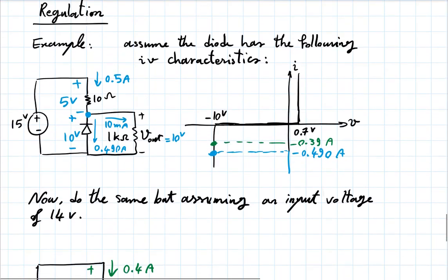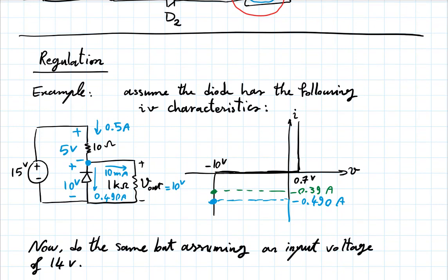Yeah, so I think the question is, we said the diode could be on or off, right, before, two possibilities. That was a diode when you were not thinking about the breakdown mode, right? So this horizontal line continued until minus infinity, basically, if you didn't have this, right? So the IV characteristics only had two regimes, if you want, the on part and the off part. Here there's a third possibility, that it's on in the reverse mode, if you want. This is called breakdown, as we mentioned. So you have to consider three possibilities, this, or that.